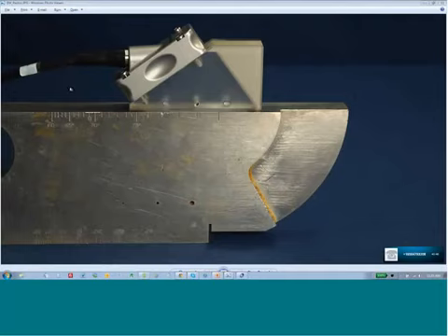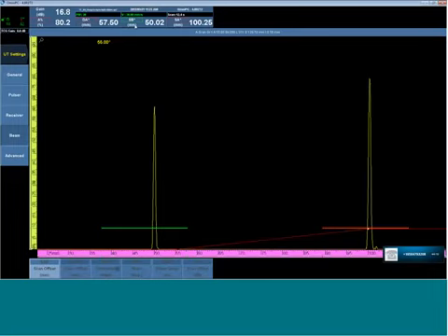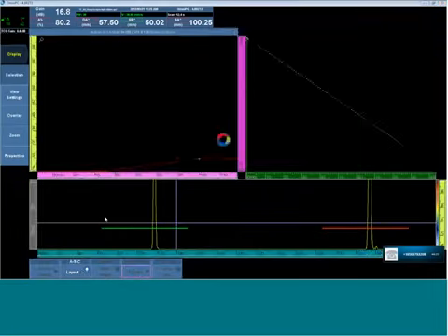Okay, what that gets us in the software, and again, here we see a typical A scan. Here is the reflector from the 50 millimeter target, and this is the reflector from the 100 millimeter target in sound path. Menu display, AS and C scan. So I took a clock inspection after wedge delay and velocity calibration to verify the accuracy of the inspection.